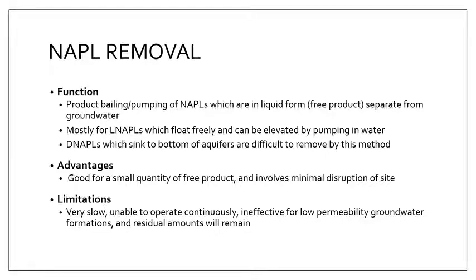Note that most NAPLs or your light NAPLs have low density and flow freely and can easily be elevated to the surface by just pumping in water. Alright, so this is just doing it by the displacement method. However, if you are dealing with dense non-aqueous phase liquids or DNAPLs, they just sink to the bottom of the aquifers and they're impossible to remove by pumping in water.